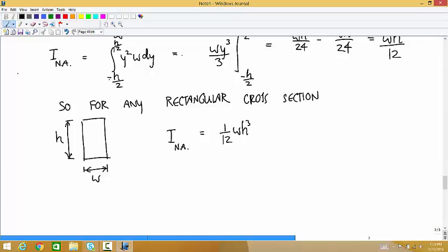Any questions about that? Is that why they do those kinds of things in aircraft frame builds? Yeah, exactly. And it's why I-beams are the shape that they are. An I-beam has a very high value of moment of inertia given the amount of mass that's put into it. And that's what they're trying to do, just make something that's resistant to bending.